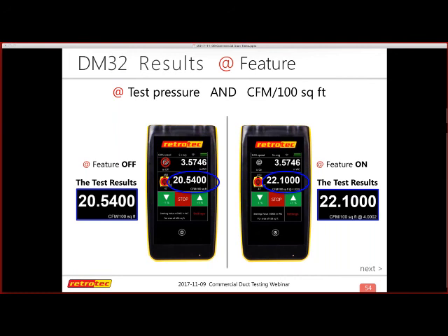It's only set speed. Whenever people say, oh, this thing doesn't work, it just jumps around, it's because they're using set pressure. So do not use set pressure. It's only set speed. It allows you to get the fan to engage in lower pressures and build up to what you're headed for without it overcompensating or over pressurizing the flex and the duct itself and the unit, so it ends up competing against itself and causes some vibration or gets the flex duct jumping around. So again, set speed is the only way to go for commercial duct testing.